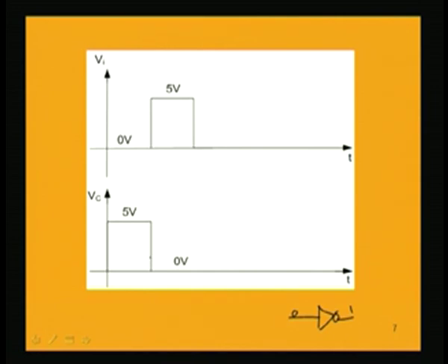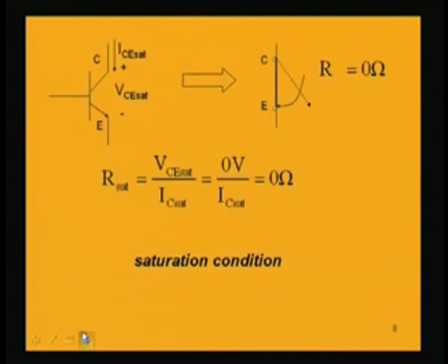So, the transistor is operating between saturation and cutoff, and if we look into the transistor operating in saturation and in cutoff, we can see that these actions are nothing but the actions of a switch. Again, if we consider the transistor under saturation, this is the transistor symbol where we are using a common emitter transistor. Suppose it is the condition when it is operating in saturation, then Vc in saturation, which we have seen, is almost equal to 0, and practically this value may be either 0.1 or 0.2, but very small.